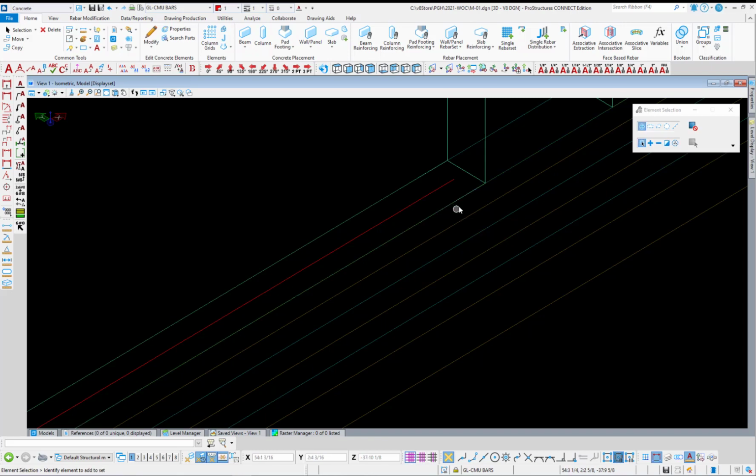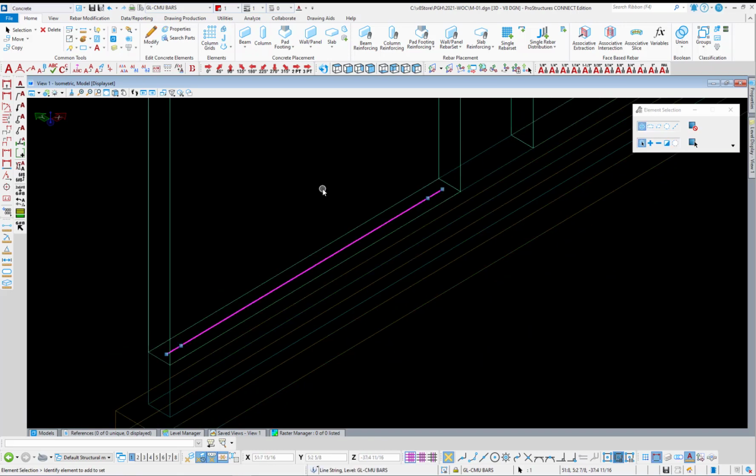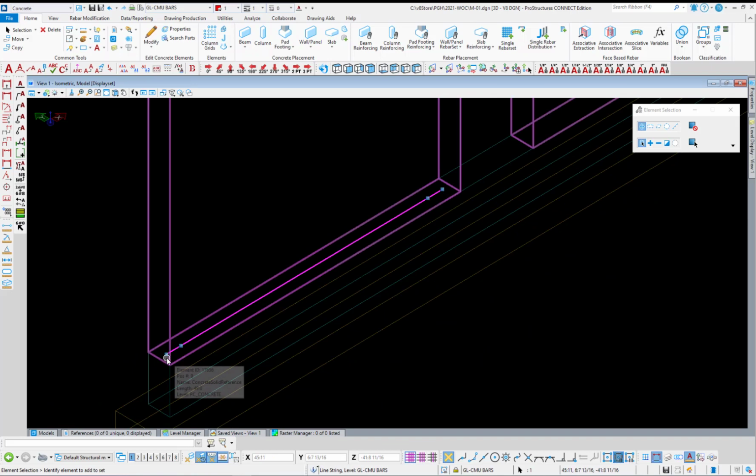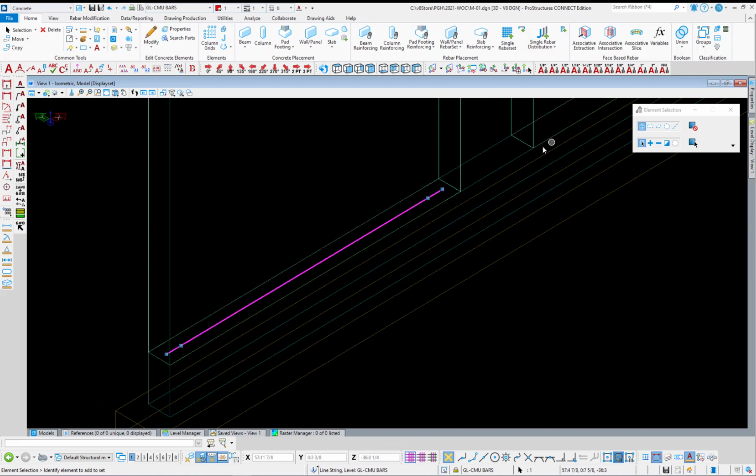So what did I do? I've created a line with some vertices, which you can see. First one's 4 inches in, puts me in the center of my start and finish block, and then 8 inches over for the block next to it. So this gives me my 2 bars in the corner and my 2 bars at the opening, plus it gives me a run to place the spaced bars at properly. Now, in this situation, the contractor is requesting 4-foot lifts. So I'm just going to offset this bar up to 4 foot.